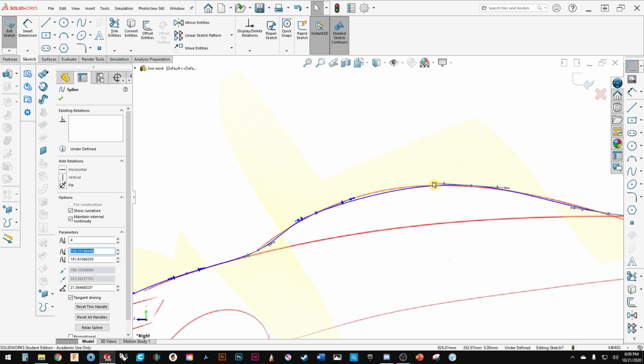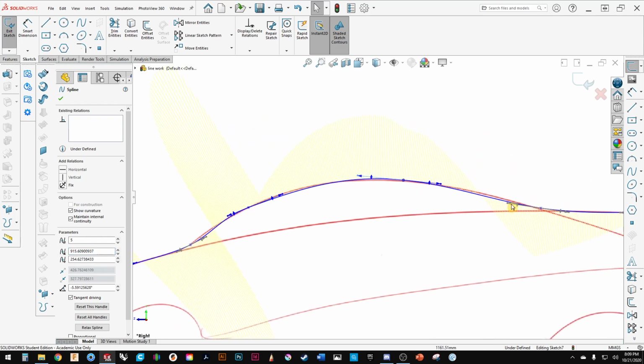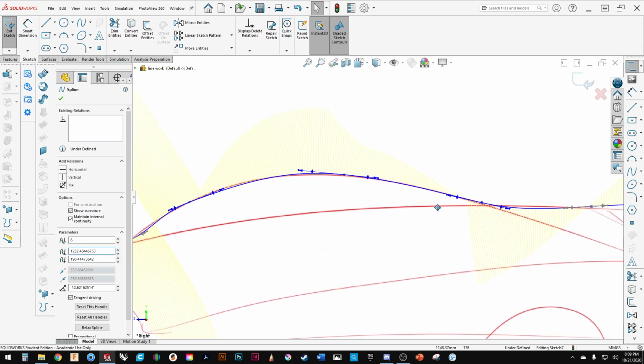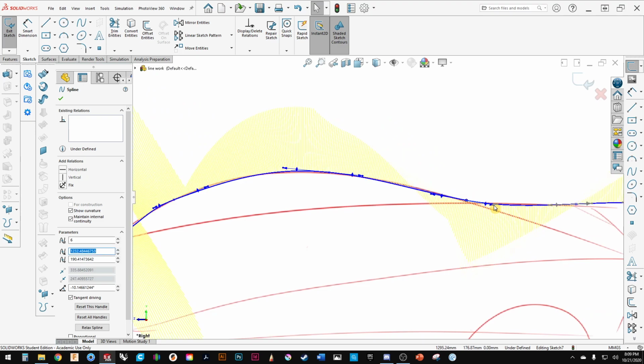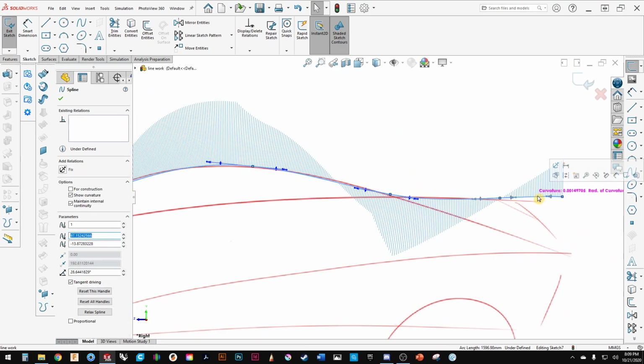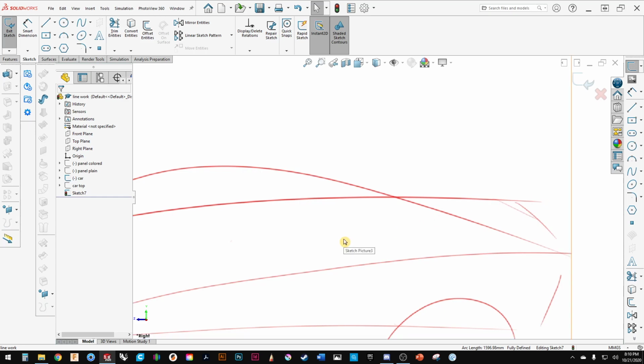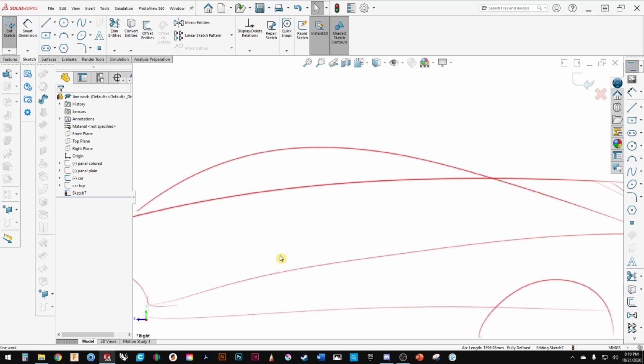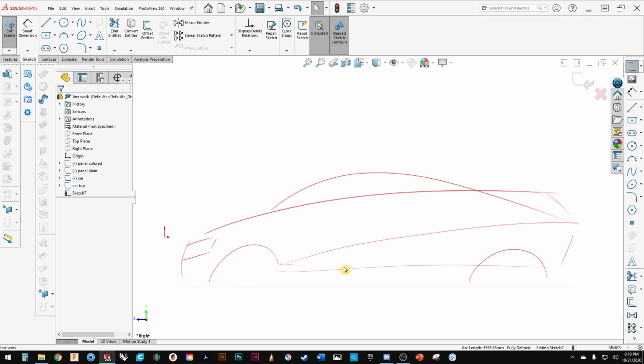So if you are trying to use splines and have a whole lot of points, it can be cumbersome. I personally will never use more than maybe 4 points at the max. I would rather build multiple curves, because what I can do is build multiple surfaces and then intersect them later. So again, blocking in my primary things.